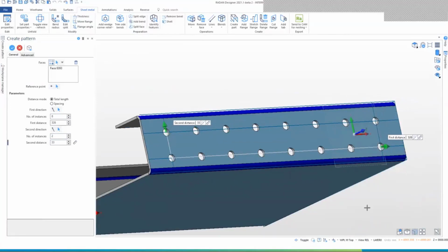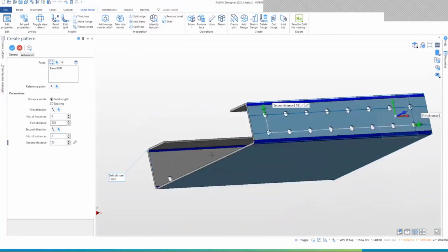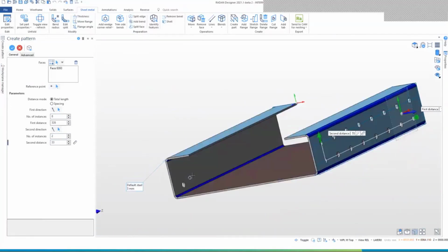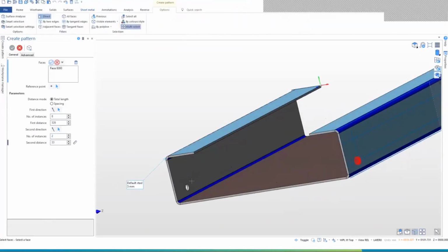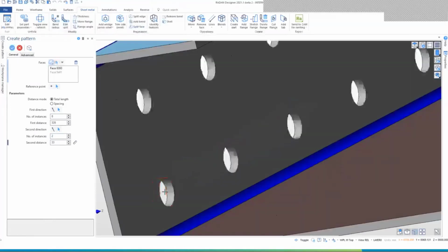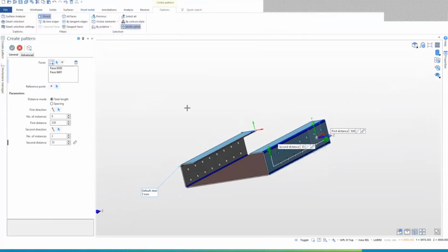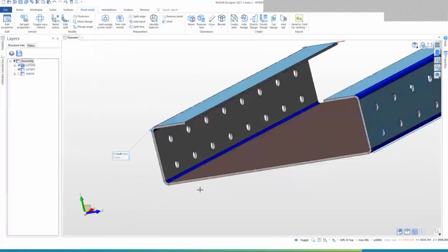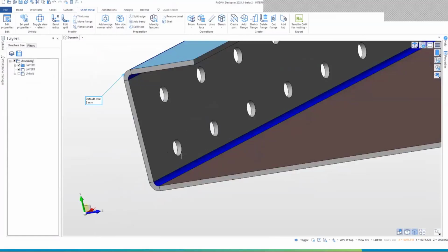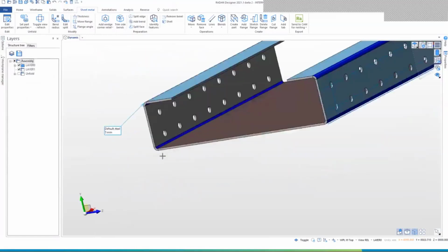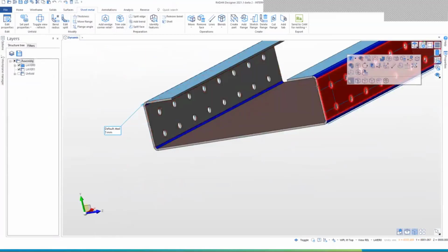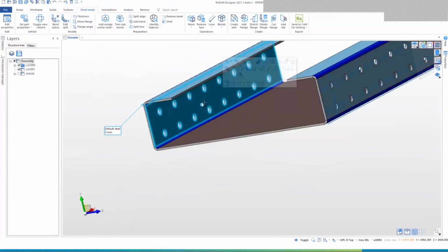I can use existing lines, vertices, and so on. If I include this one into the selection, it will get propagated on both flanges. If I were to forget including this one, what I could do is create a work plane on this face and just project this face onto this one and use new geometry to cut the other flange with the cut flange command, if that makes sense.